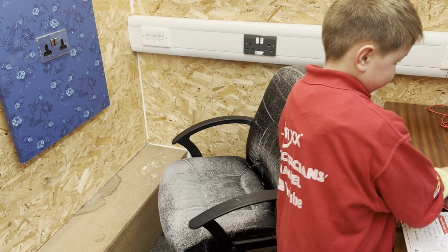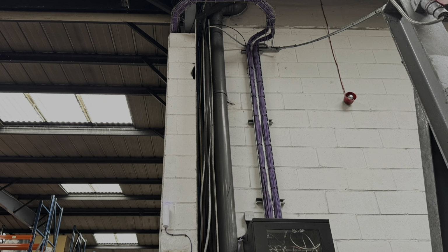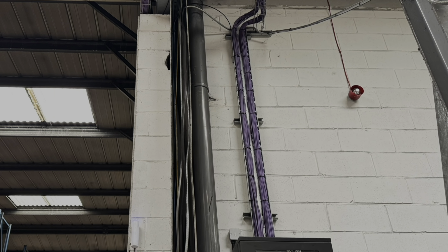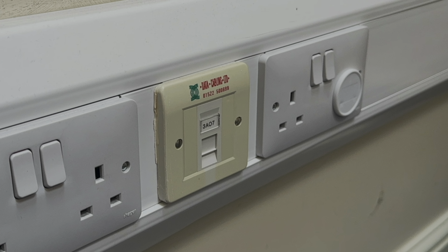So to avoid this interference, we need to separate the band 1 and band 2 cables. This could be just by moving the cables further apart, but this is not always possible or practical. Certainly in offices where data connections for internet and power are required to the same positions. Dado trunking, like the one here, offers separation between band 1 and band 2 cables.